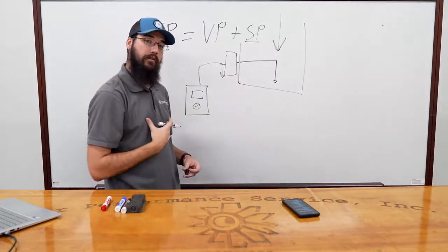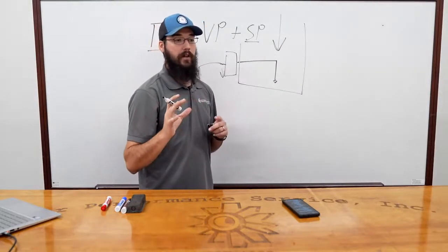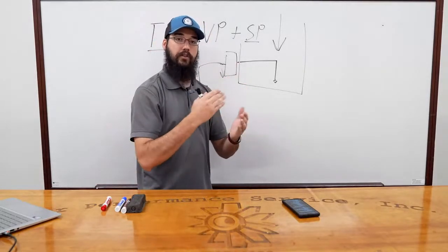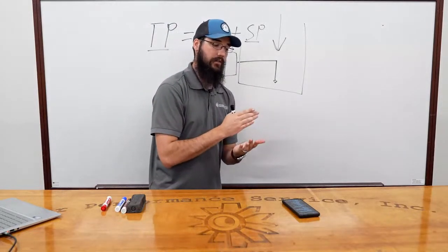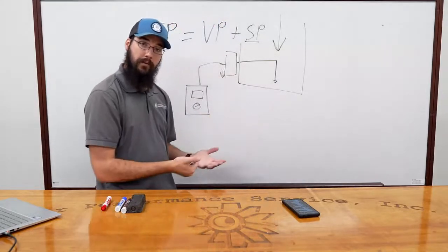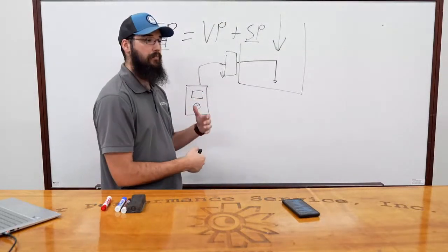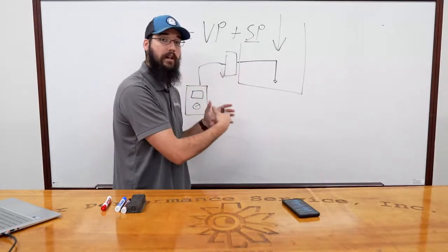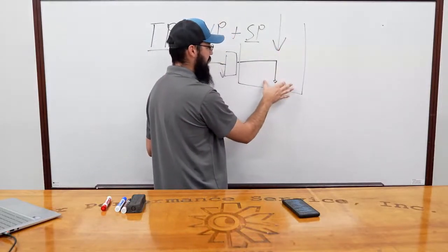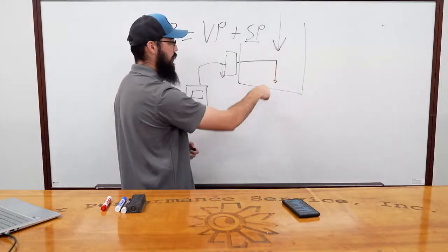My very first one was a MagnaHelix. MagnaHelix are super effective, but they come with their challenges. With a MagnaHelix, they're very positional, and there's a lot of things you have to calibrate. It takes some technical skill when you first try to start to use them. Manometers, digital manometers especially, have really simplified this process for us, to where they self-calibrate, and they do a lot of things for us and make it simple. Anyway, make sure you're facing with the airstream with your probe sticking in.